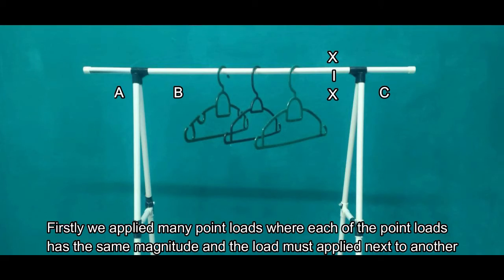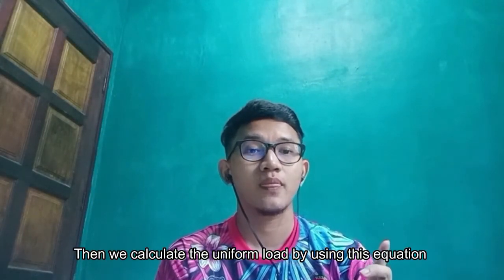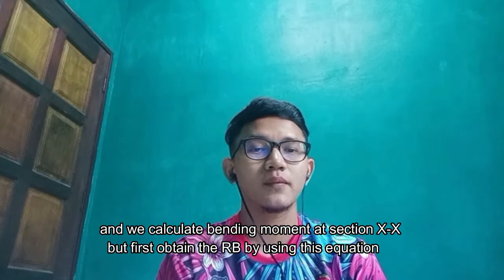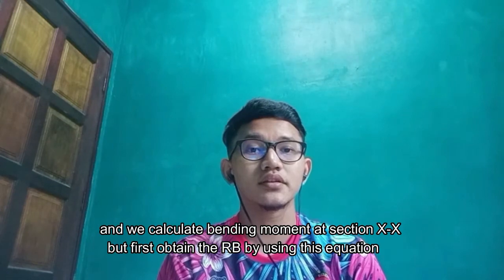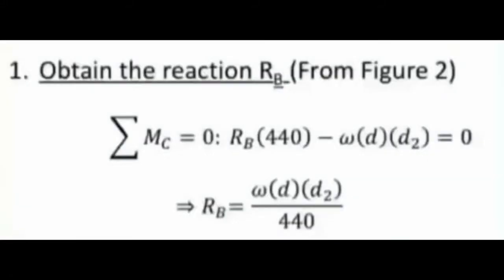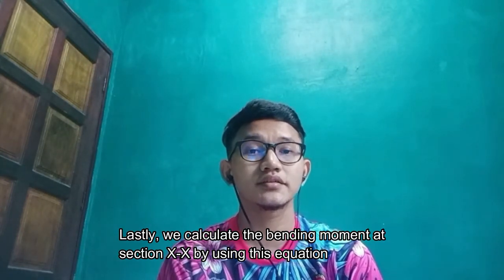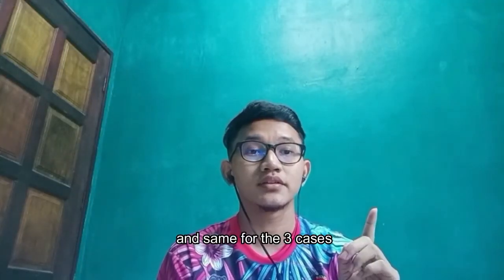Firstly, we apply many point loads where each of the point loads has the same magnitude and the loads must be applied next to one another. Then we calculate the uniform load by using this equation. Next, we calculate the bending moment at section XX. But firstly, we obtain RB using this equation. And lastly, we calculate the bending moment at section XX by using this equation. And same for the 3 cases.